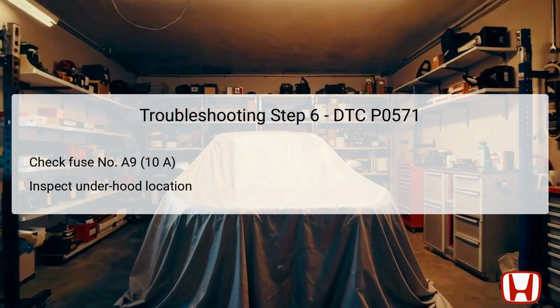It's essential to always inspect for any signs of shorts to ground on the fuse circuit as well, as this can lead to recurring issues following replacement and could present similar symptoms as DTC P0571.